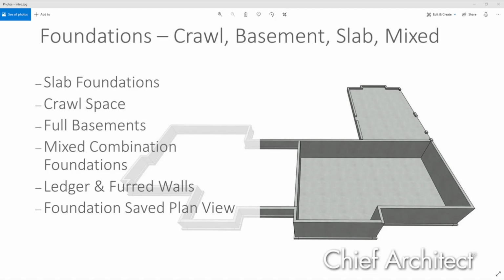And as soon as I go to build foundations, the program gets upset that the floor for the garage is 28 inches lower than the house. So it takes that stem wall, even though I have a slab for the garage, and it ends up throwing this stem wall on top of the slab foundation for the garage.